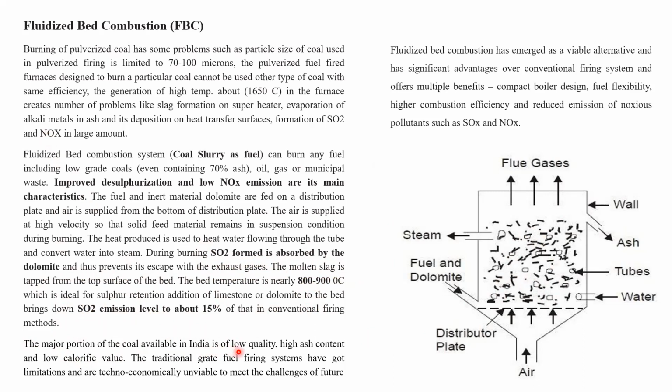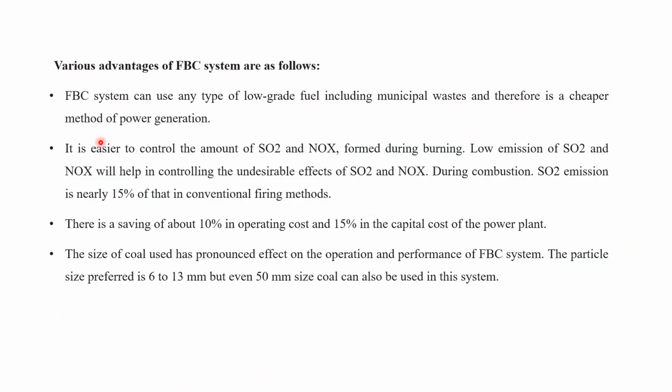The major portion of the coal available in India is low quality, with high ash content and low calorific value. The traditional grade fuel firing systems have limitations and are techno-economically unviable to meet the future. So fluidized bed combustion has emerged as a viable alternative and has significant advantages over conventional firing systems, and offers multiple benefits, that is compact boiler design, fuel flexibility, higher combustion efficiency, and reduced emissions of NOx and SOx. Okay, this is in brief about FBC.